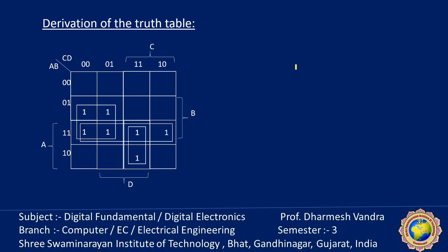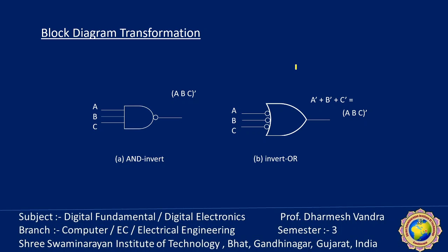Now put it in a Karnaugh map, and with the help of the Karnaugh map derive F equal to AB plus ACD plus (BC) whole dash. So this is the same expression which we found out earlier, the correct answer. In this way, we can also analyze the NAND circuit. It is sometimes convenient to convert the NAND logic to an equivalent AND-OR logic diagram to facilitate the analysis process. By doing so, the Boolean function can be derived more easily without applying De Morgan's theorem. The conversion of the logic diagram is accomplished through a process reverse from that used for implementation.